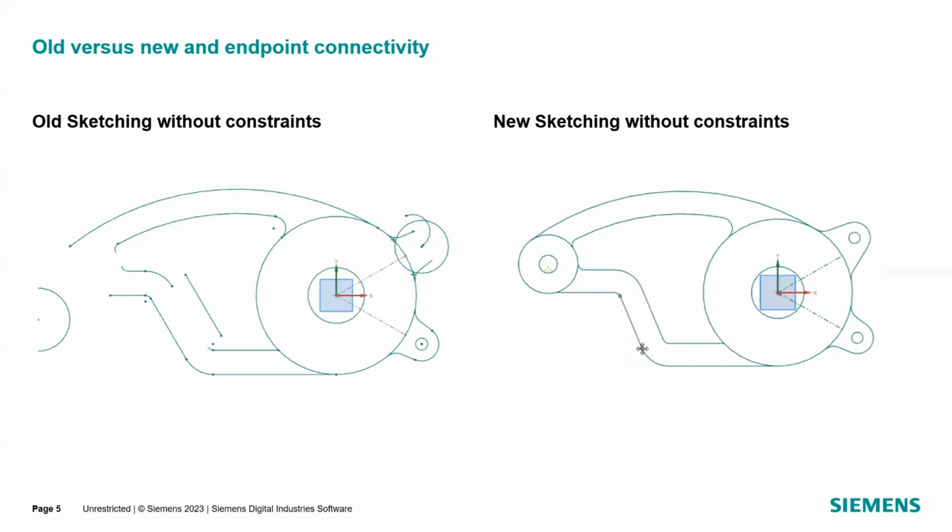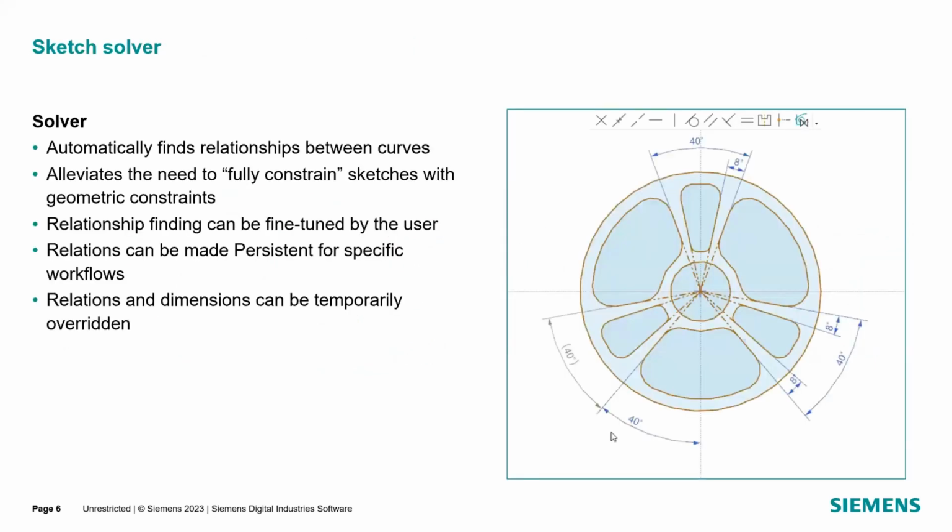For all the geometry that is input for your design, you can see on the screen, as we move and adjust, that the sketch is adapting with that. And the ones you see on the screen have no dimensions, no geometric constraints or anything like that. It's just using the geometry and the solver to do that work. And so that's really number one, the new solver.